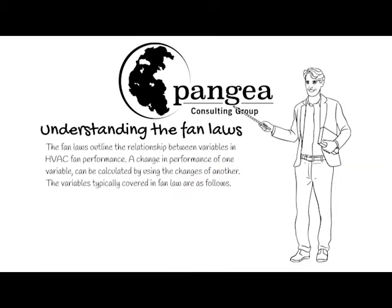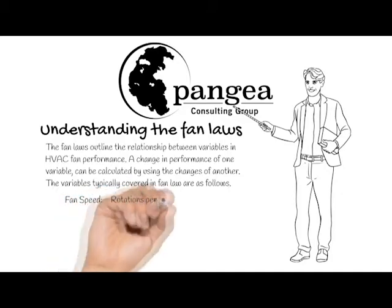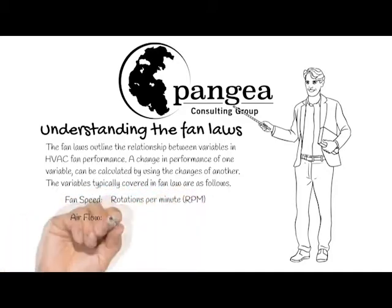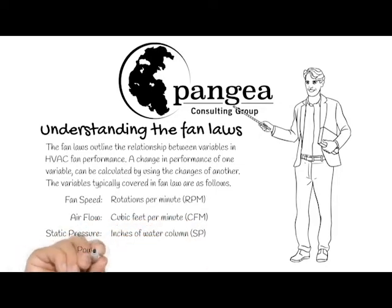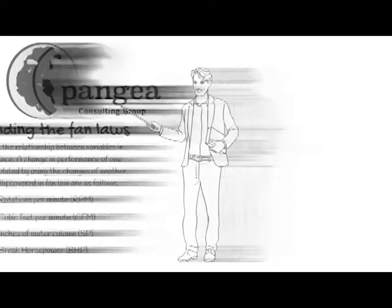The variables typically covered in fan law are as follows: fan speed, rotation per minute; airflow, cubic feet per minute; static pressure, measured in inches of water column; and power, measured in brake horsepower.